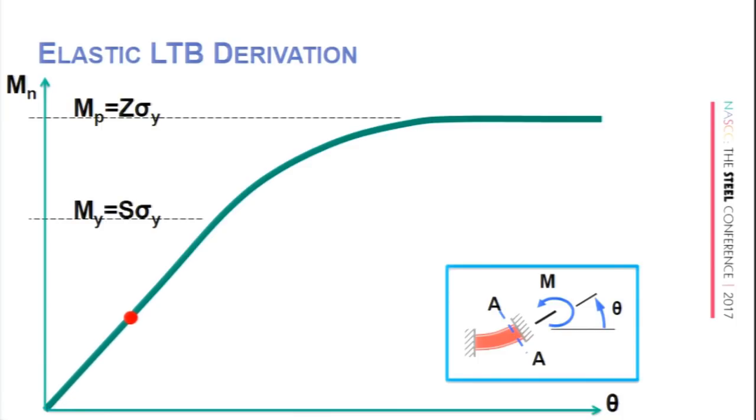And as we move up the curve, and now we're looking at our nominal moment capacity and our end rotation. See, here's that easy way to do it. Same difference. This is half my beam, right? Half a simply supported beam. Cut it in half, right? At where I apply the load, it's like a fixed point, right? We hope it stayed fixed and it didn't move. But you saw, because there was a stiffener there right under the load, because we didn't want to crush the web under that load, there were stiffeners there. But on that one test where all the local buckling was on one side, did you notice that that stiffener wound up looking like this at the end?